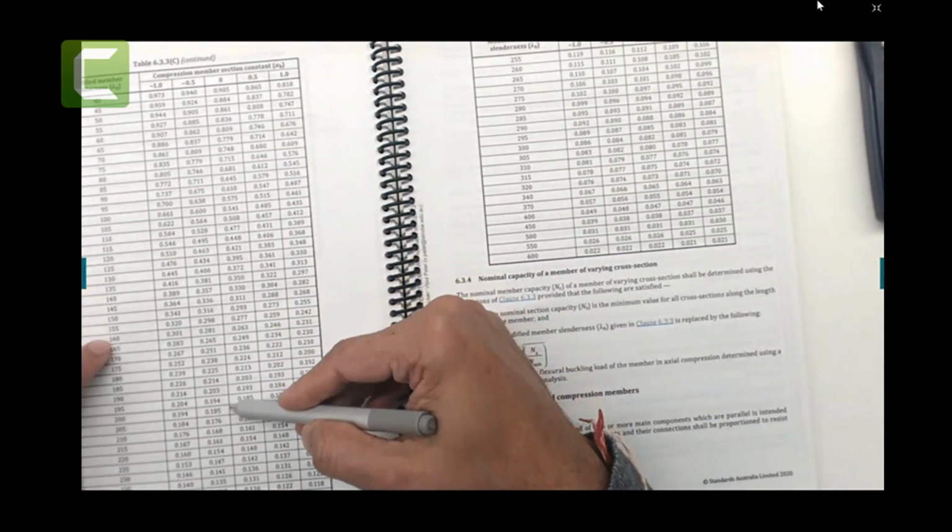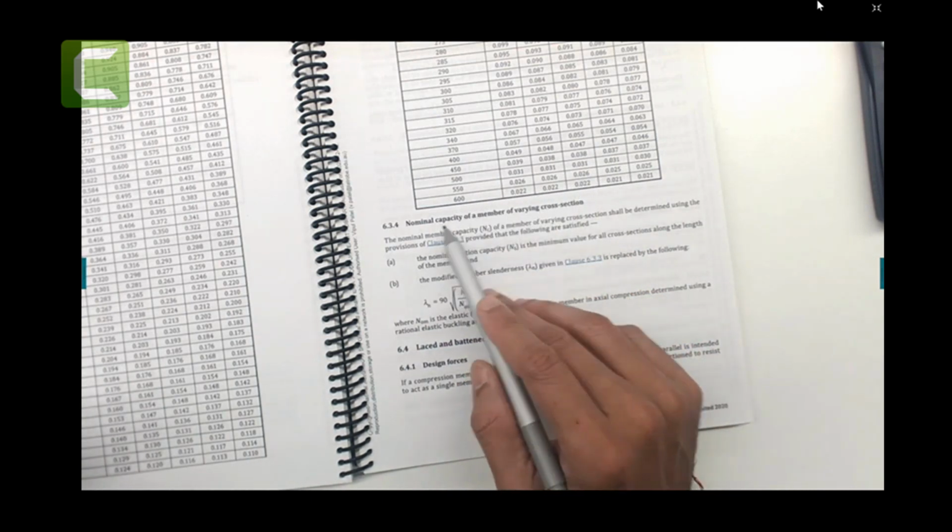The longer you get, the more the penalty. With the length increasing or the radius of gyration reducing, the penalties are increasing. Look at that. Sometimes your capacity almost becomes 0. There is no column here. Look at this last one, 600. For the longest columns, they already put just 0.00. There is nothing. If you have 100 and you multiply 100 by 0.022, what do you get? Nothing. What's the point of using it? That's right.